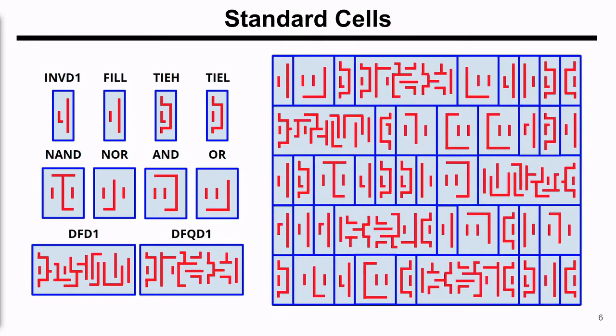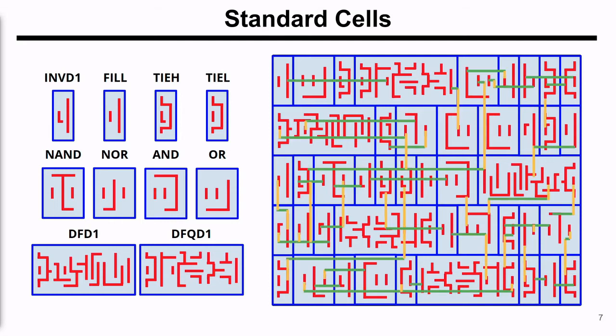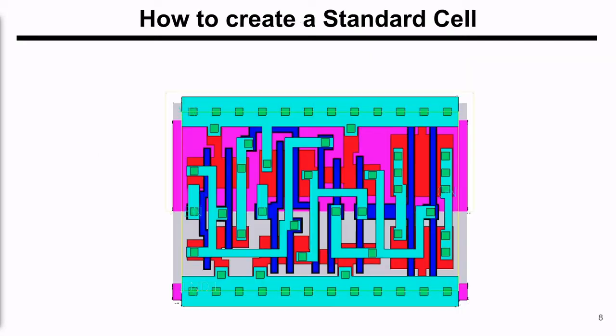The placement of standard cells follows a grid, which is usually defined by the smallest cells possible. Other cells have a horizontal size which is a multiple of this minimum size. Another grid is defined to perform routing. These routes will integrate the circuit in the intended behavior according to the netlist. Each one of the standard cells contains ports where the routes can connect. These grids are defined by the technology design rules.